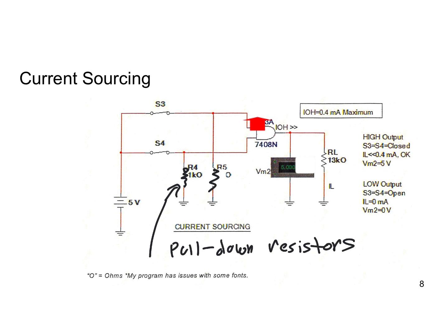So all inputs must have either pull up or pull down resistors at some point in order to provide consistent, expected, reliable voltage levels. Okay, this little note here, that should be an ohm. Anyway, this is showing an AND gate. Could be any gate, doesn't make any difference.